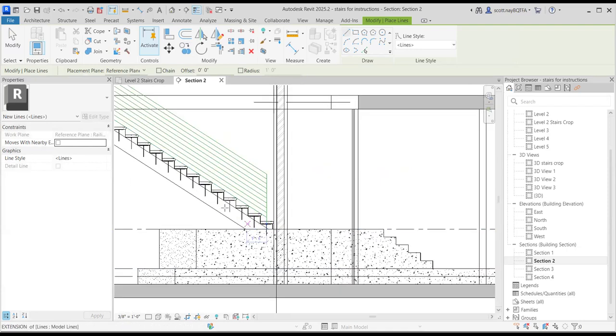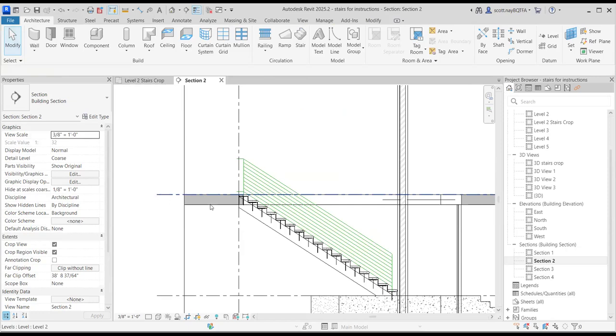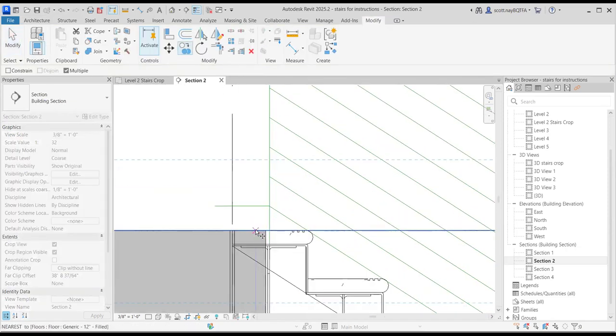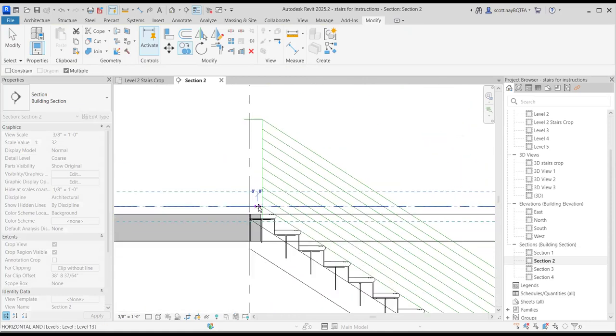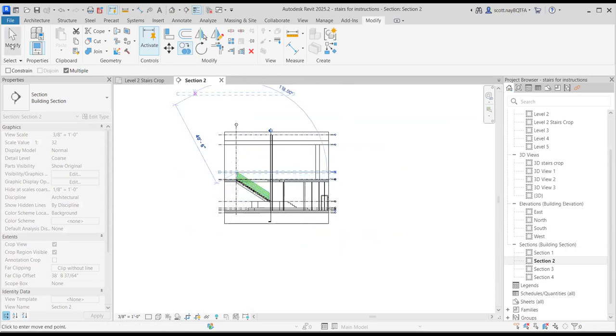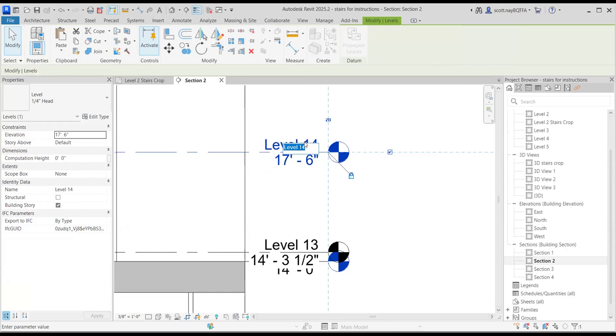I'm going to come down. Well, first I'll copy the levels. Grab this level, hit copy. Gonna come up to the here and here. I'm gonna rename them. And we're gonna call this second floor flat. And they're gonna call this one second floor round.